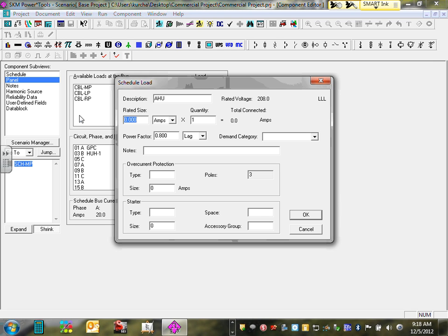We have 100, 125, no, the full load amp, when you guys calculated it. Do you have it from the schedule? It should be on your mechanical schedule. What is it in your mechanical schedule, Jeff? Was it 82? I can't remember. The air handling unit full load current should be in the first. There's the horsepower and then the full load current amp. 34? 46.2. Thank you. That sounds about right.